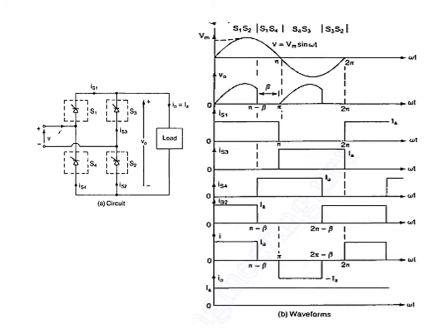For inductive load, the freewheeling path must be provided by switches S1, S4 or S3, S2, and the firing sequence should be switch 1, switch 2, then switch 1, switch 4, followed by switch 4, switch 3, and last switch 3, switch 2. So this should be the firing sequence for inductive load with freewheeling path. Next method is symmetrical angle control method.